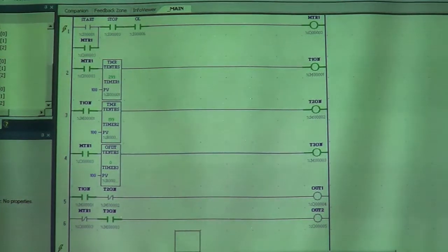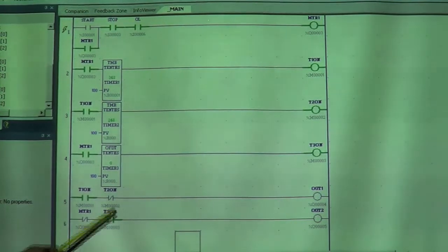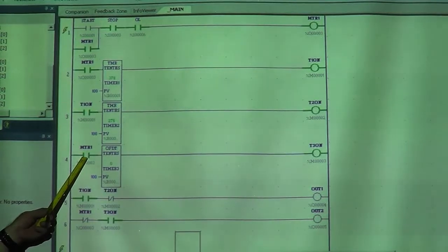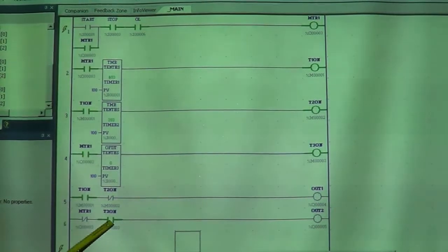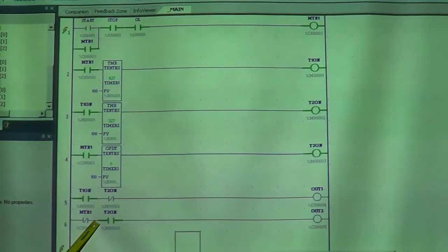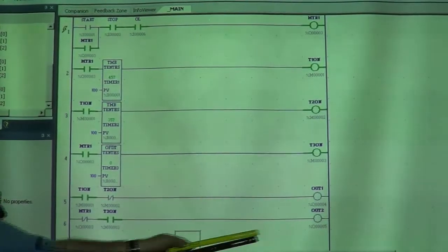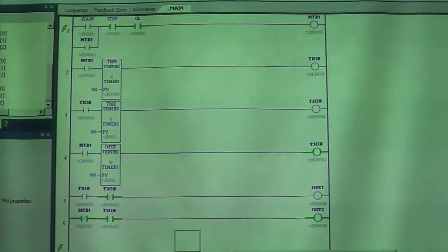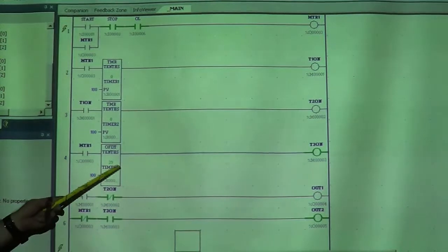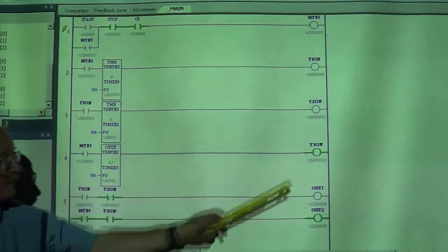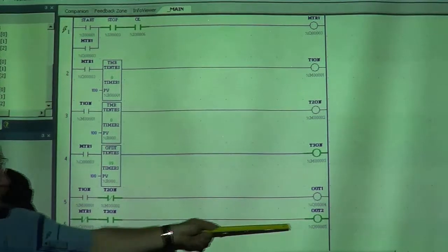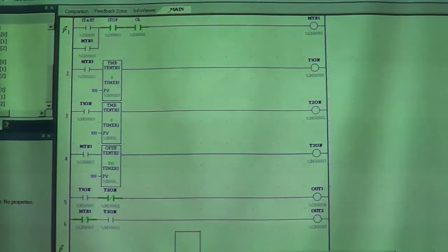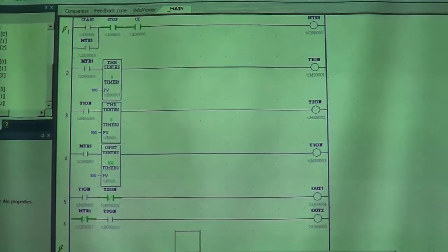We went through our startup sequence. You see T3 is on, and it will stay on when we turn off motor 1. So when motor 1 turns off, that will stay on. This will allow power flow through it, and our output 2 will happen. So I come over here, hit the stop button. There we go, motor's off. The timer is still on because it's an off delay timer. Both of those allow power flow to turn on our output 2, or brake, or whatever it is that's happening for 10 seconds after the motor shuts off. Then we're done. Very simple.